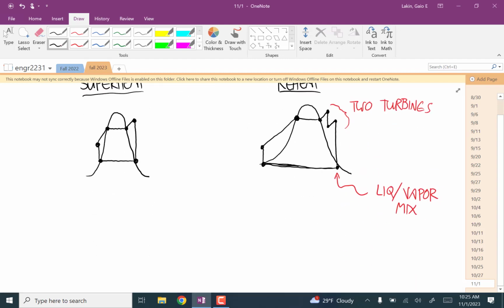Okay, so the first time we talked about cycles was in the section where we were talking about the Kelvin-Planck statement of the second law, and I kind of just gave you all these measures of efficiency. Some of them you could sort of make sense out of, like it makes sense that the efficiency of a power cycle would be the work that it produces divided by the heat that you have to put into it. But then some of it, I just kind of threw, like an ideal power cycle, I said, was 1 minus temperature at the condenser divided by temperature at the boiler, and I just sort of stated that.